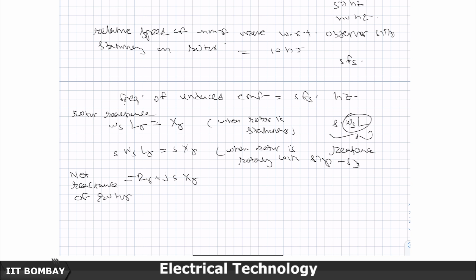That rotating MMF wave with respect to a stationary winding on the rotor, let us say the A phase winding, will again create a sinusoidal flux variation in space. So therefore there is an induced EMF in it, and that induced EMF will cause a current to flow through it, but because the rotor is not held fixed, that current